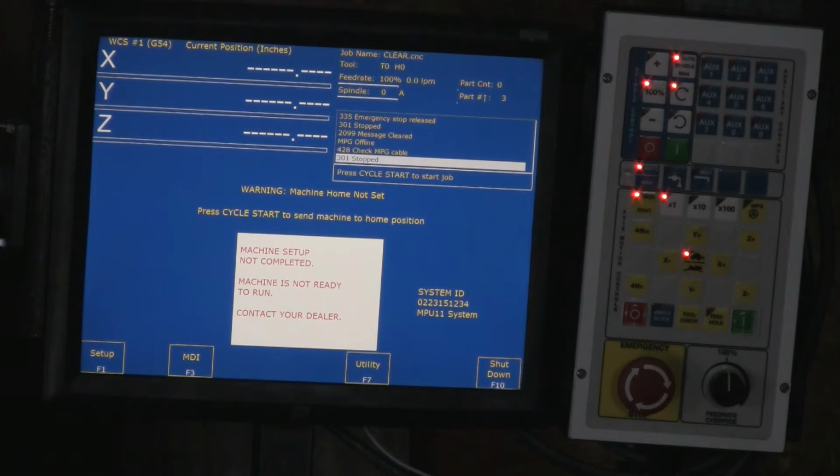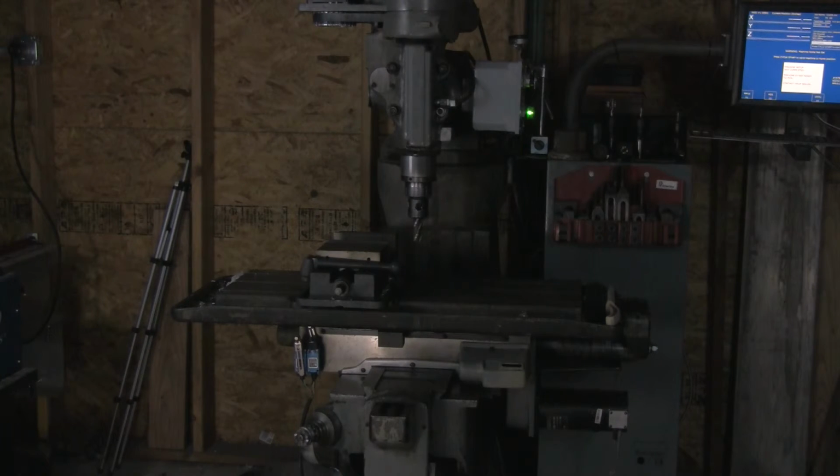So, I'm going to go ahead and switch the camera over here to the machine, and then we'll go ahead and hit cycle start. Now when I hit cycle start, the Z-axis will be the first one. Remember, we told it to go positive till it finds a home switch. And so it retracts, finds the home switch, and then returns off of that home switch and parks.